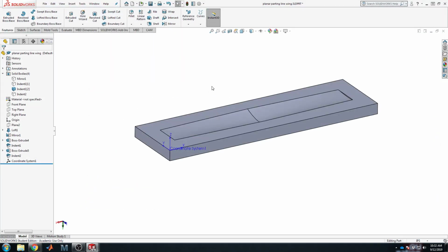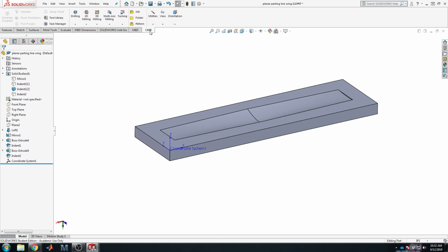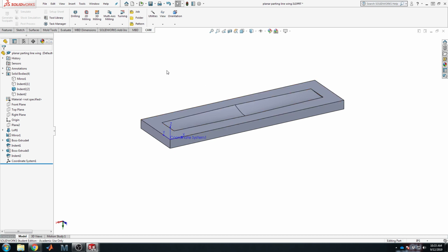There are a multitude of CAM, computer-aided manufacturing softwares out there, and they make a big difference in your happiness while generating this code. Most all of them are successful. They couldn't sell software unless it was able to generate code, but certainly the quality of the auto-generated code, the speed at which it removes material, and overall just the usability of the software is the biggest difference I see between things. So I would highly recommend HSM Works right now, at least, over some of the more default SolidWorks CAM options. And maybe you'll agree with me or disagree by the time we're done with this.